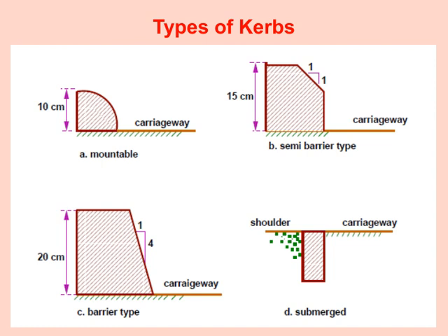For example, the vertical curb is the most typical. It provides a strong edge that helps contain the road surface and directs water towards drainage points. Then we have the rebated curb, which is slightly stepped and often used where vehicles need to access parking areas or driveways, offering a smoother transition for vehicles.